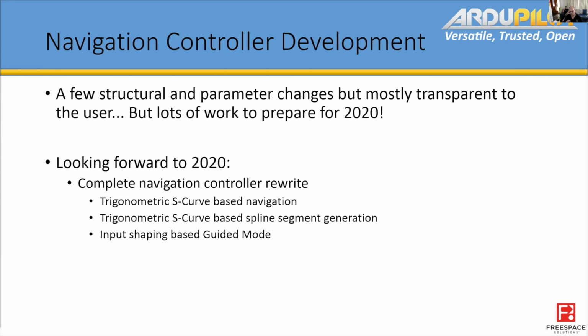All this also follows into input shaping on guided mode, taking the same attitude controller architecture and using it for guided mode. That means guided mode can potentially get an order of magnitude improvement in delay through the system, and allow companion computers to have much more tightly coupled control of the aircraft.